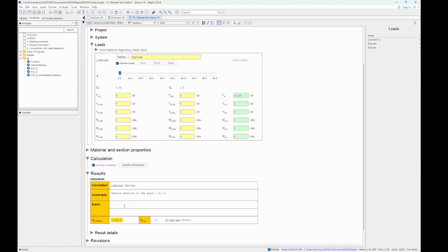And in that case, you are getting this value in addition. So let's say the active value is calculated here, of the active load case. But if you have added something additional, more than one load case, and you press calculate all load cases, then this value switches the color from gray to either green, orange or red, depending on the utilization factor for the load.